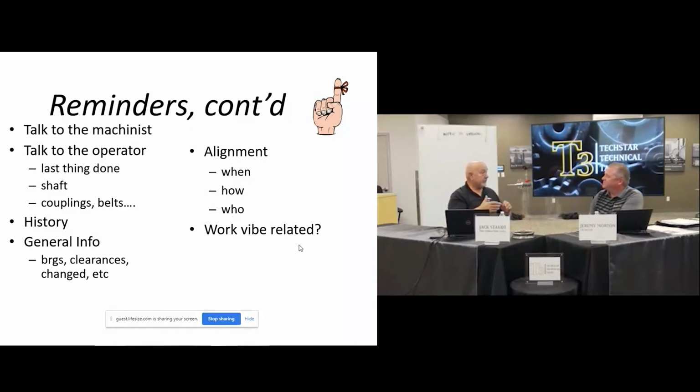And what had happened was the shim packs, it had like a Series 71 Thomas flexible coupling. The shim packs had broke. And it had an expanded metal coupling guard on it, so you could take a strobe light, and when you strobed the coupling, it was just bolts to bolts.